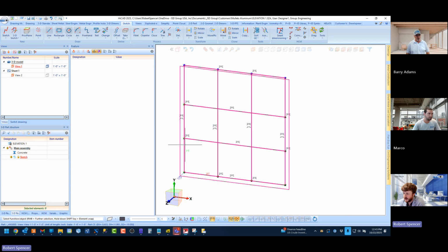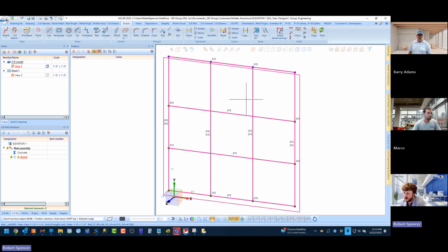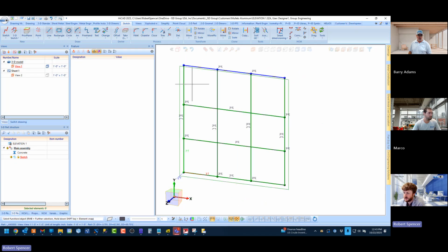And we can't have double lines. I don't think we would have created any double lines here, but it can happen when you use these clone commands. For example, if I took this line here and cloned it 1, 2, 3 times on top of a rectangle that I already had, there could easily be a double line you forgot about.